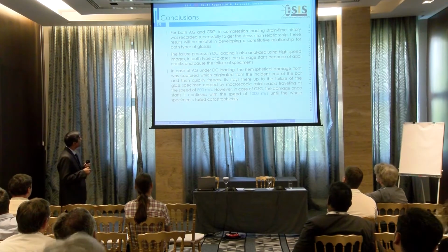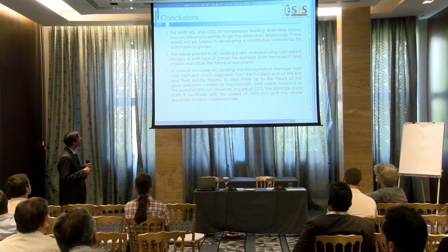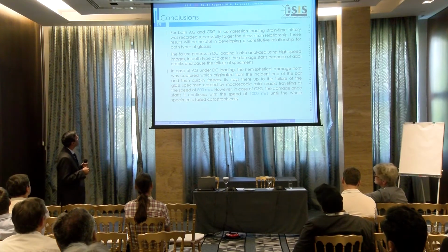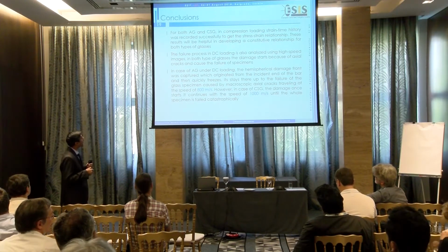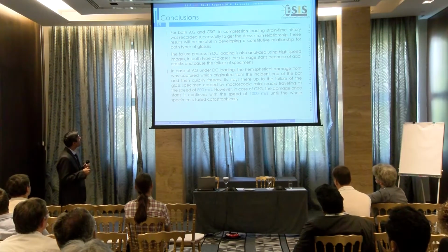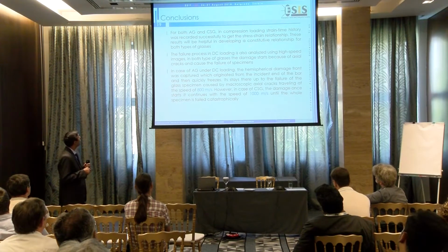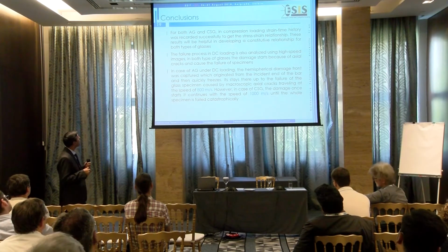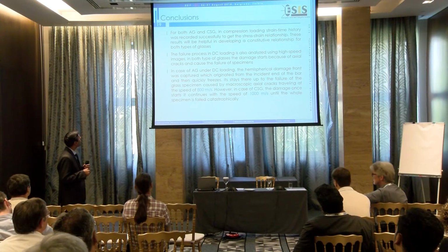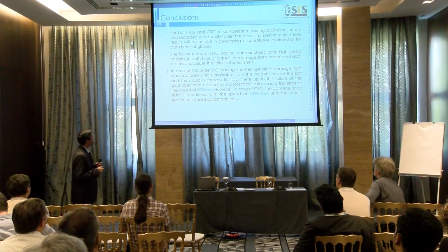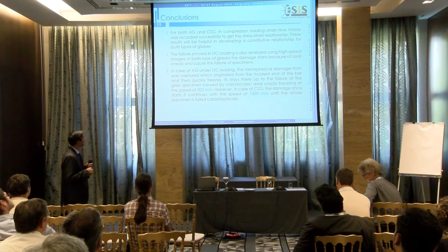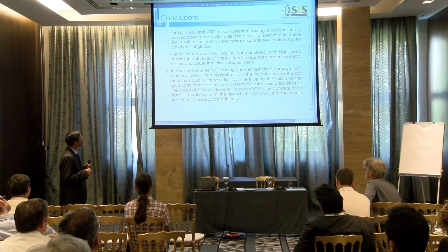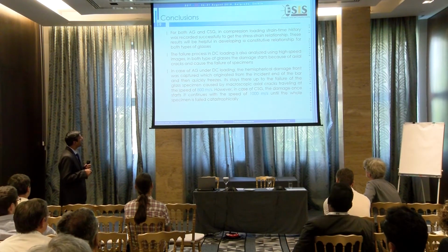And it's very challenging because the compressive strength of the glasses is very high as compared to their strain. So we successfully obtained the strain time curves during the experiments for both static and dynamic, and we are able to get the stress strain curves. These curves will be useful to develop the constitutive relation for simulation purposes. And the failure process in both types of glass is because of axial cracks, and the axial microscopic crack speed is 800 meters per second for the annealed glass and 1000 meters per second for the chemically strengthened glass.